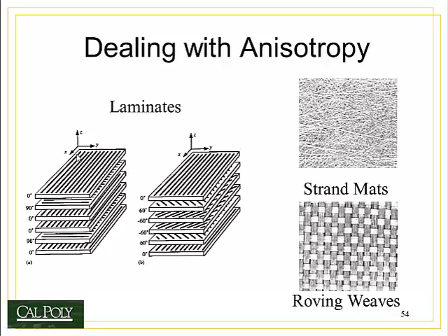The last choice is called a laminate, and we already talked about these a little bit. So here's some examples of where I have a unidirectionally reinforced composite with all the fibers running the length of the composite in one direction. This is called the 0 degree orientation. Then I lay down another layer of composite where all the fibers are going 90 degrees to that. And then I can put down another 0 degree, another 0, a 90, and another 0.